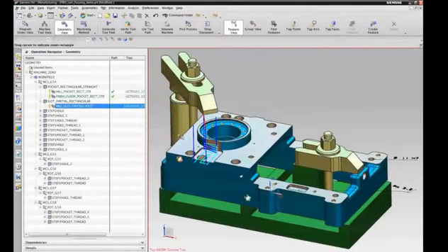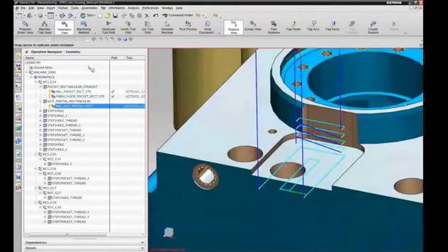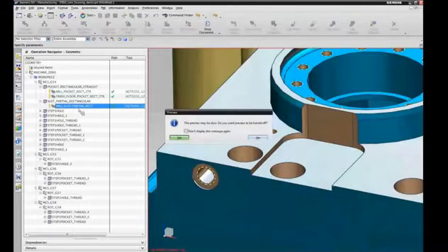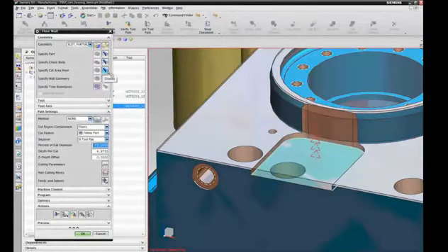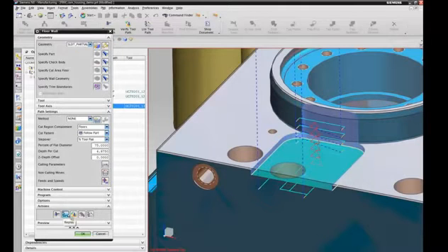I'll zoom in a little bit. That area is a milling operation, and the system basically knew what my floor is and what my walls are. It's a floor wall operation, a new NX floor wall operation, and it basically selected a follow part operation with a certain step over and depth of cut, and that's the toolpath that we just generated.